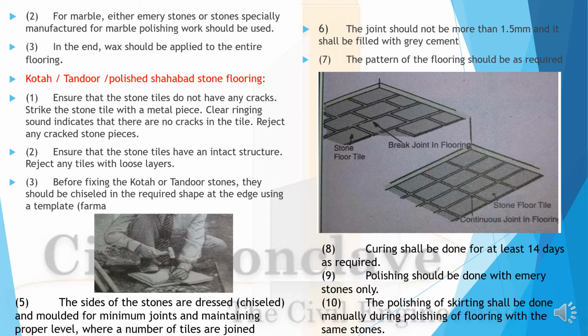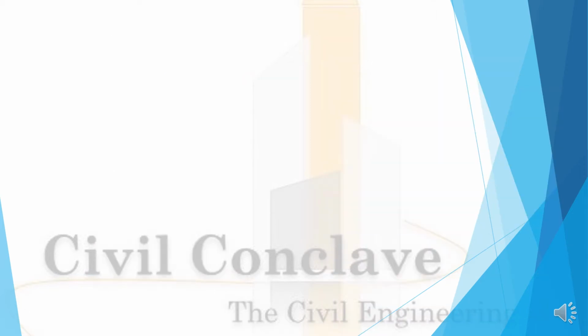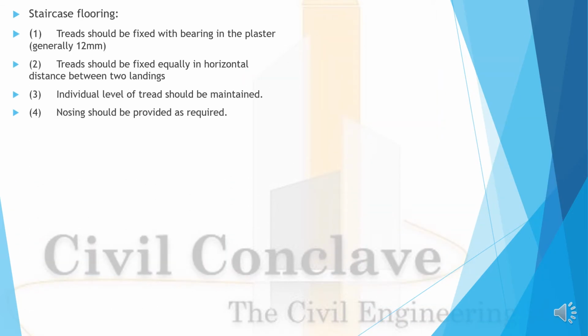Curing shall be done for 14 days. Polishing should be done with emery stones only. The polishing of skirting shall be done manually during polishing of flooring.